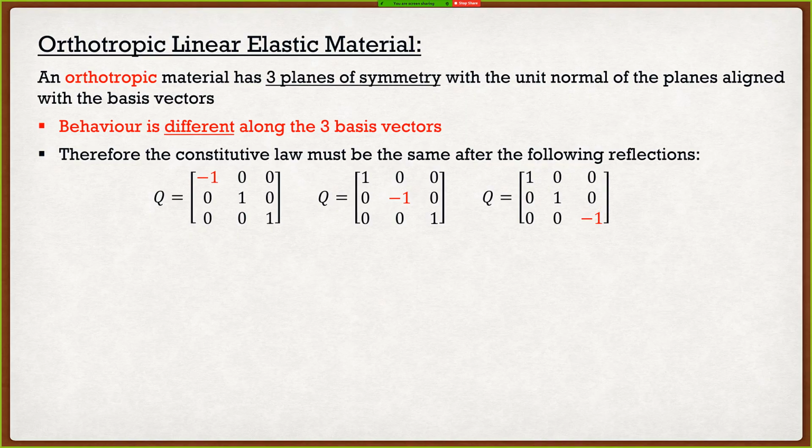Well, this is the only part of the course where we have to realize that even though we express our constitutive law as a 6x6 matrix, it's actually a 4th order tensor. It's not a 6x6 matrix. So if I were to transform it, I basically go to this equation over here, where C prime ijkl is equal to Q_mi, Q_nj, Q_rk, Q_sl times C_mnrs.